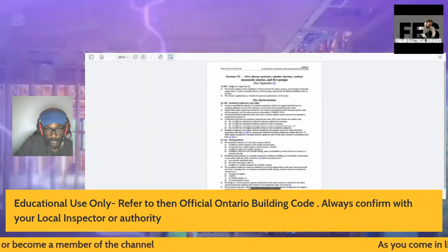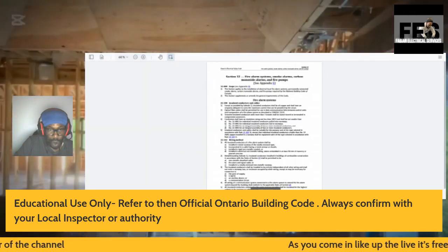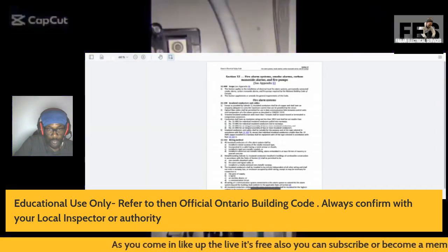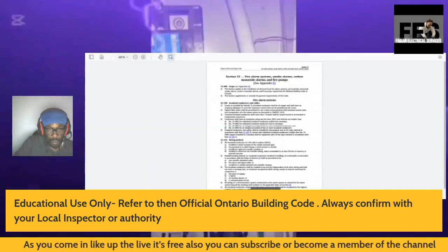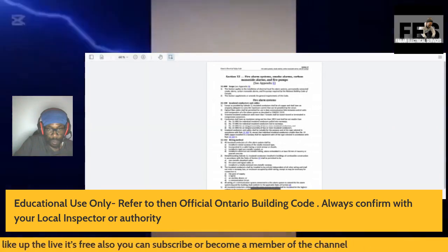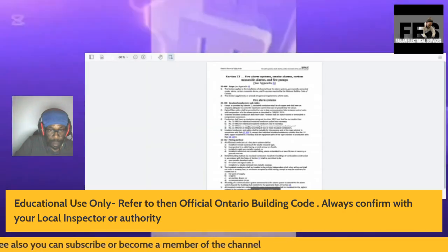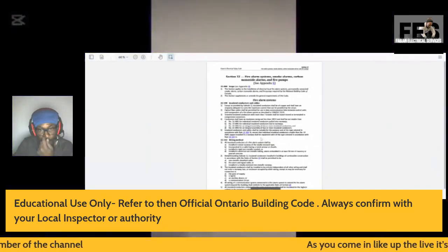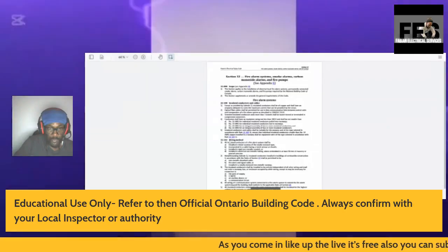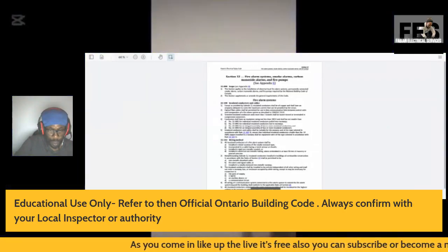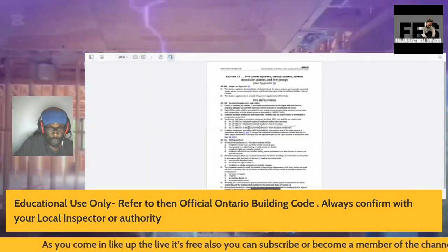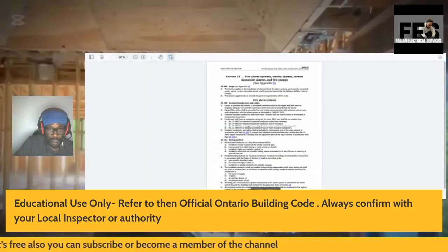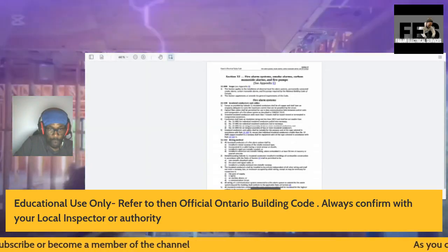Insulated conductors and cables shall be suitable in accordance with Rule 12-102, Subrule 3, except that individual insulated copper conductors shall be of the type selected in accordance with Rule 12-122. So this is basically sending you to this rule after you have read this one here.